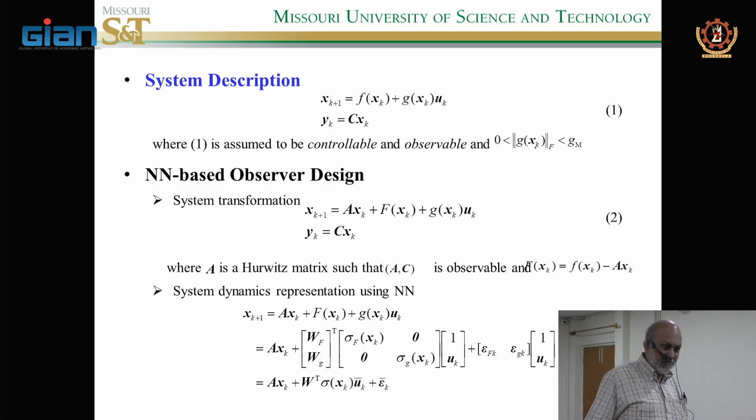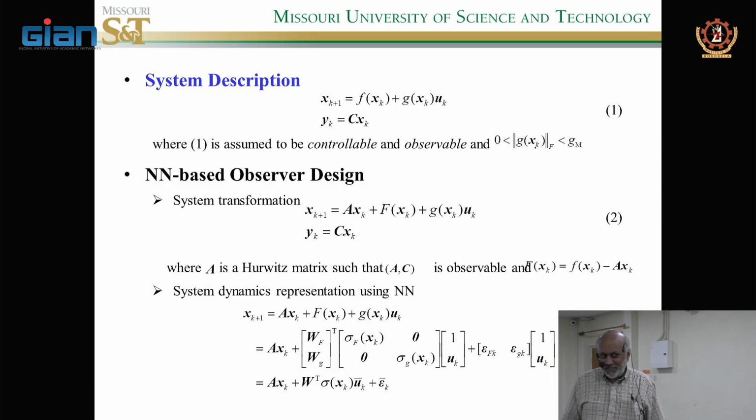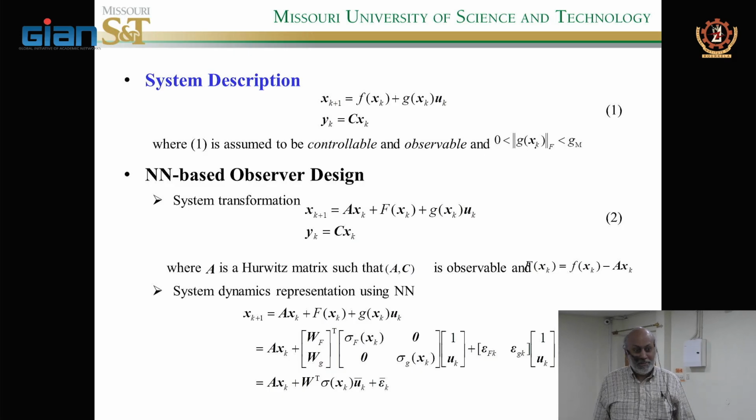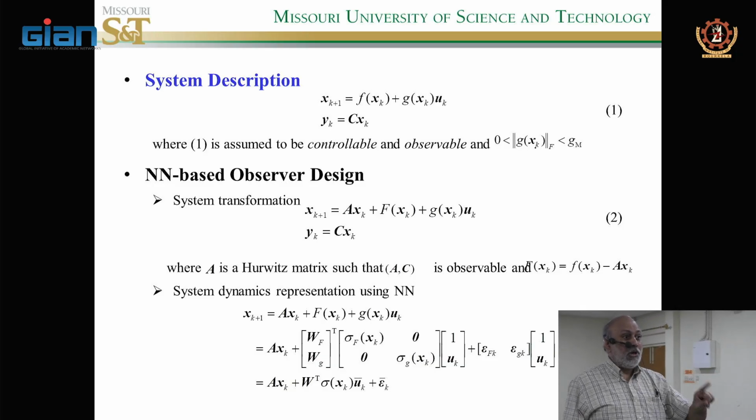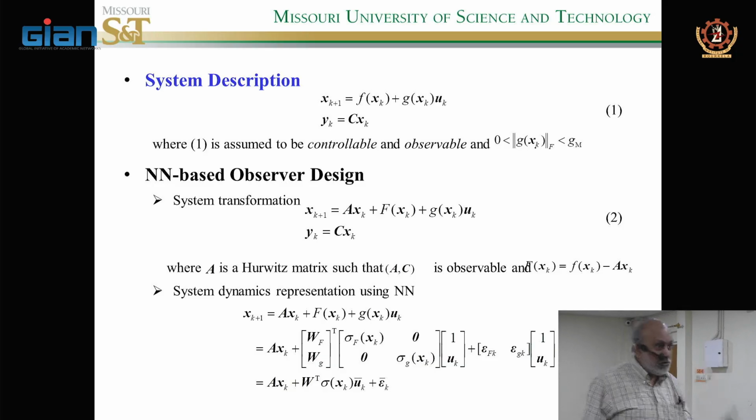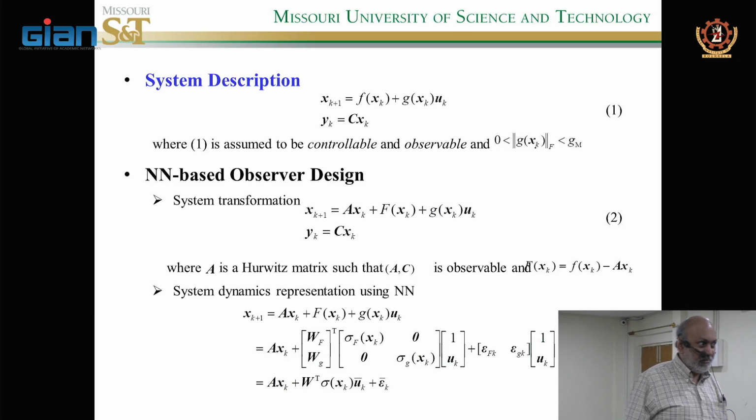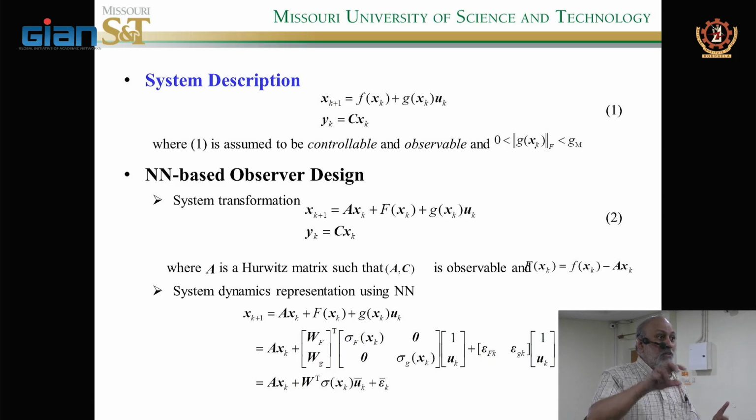Okay, which one? Right, right. That's what I am asking, yeah. So you can change it with the control input. Physically you can add some actuator there. Okay, that's what I want. So if the system is not controllable, there's nothing we can do. The only thing we can do is physically change the actuator location or add an actuator.